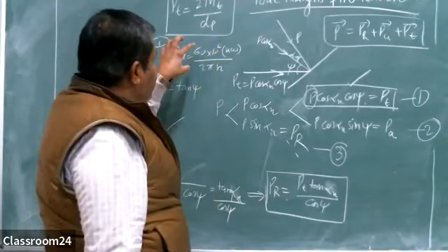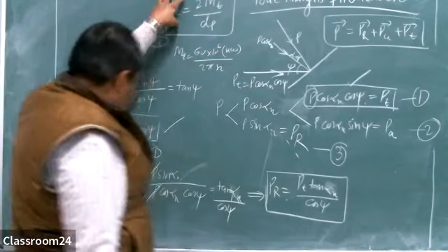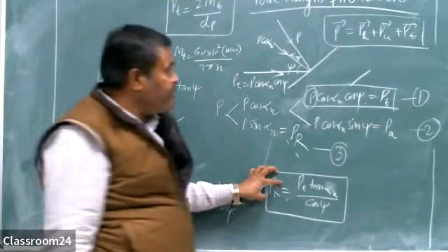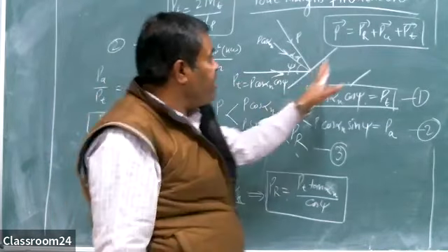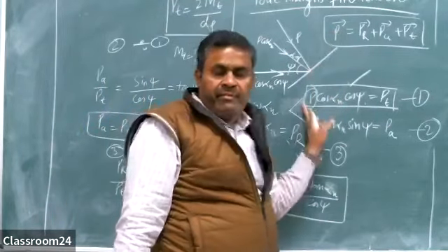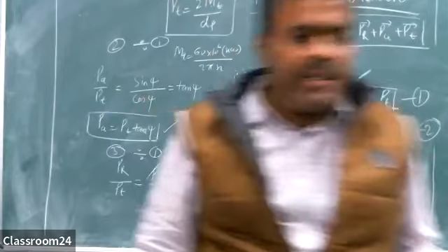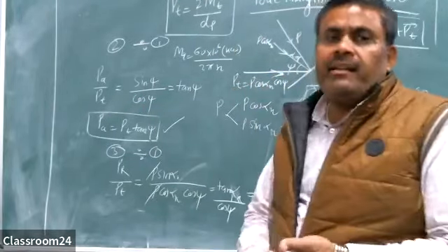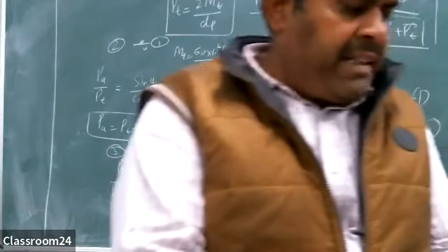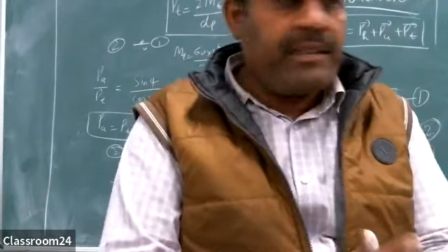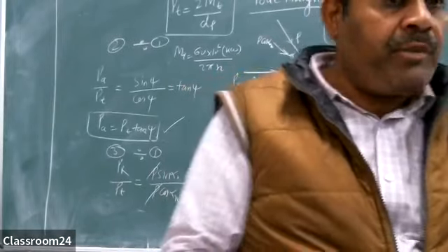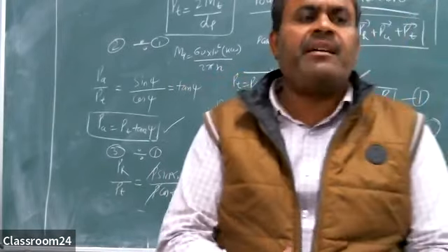So we first calculate the torque, then PT, then the axial force, then the radial force. In this situation, we do not need the resultant force. So this is the force analysis of the helical gear. I think it is clear: three components in helical gear, while in spur gear there are only two components.